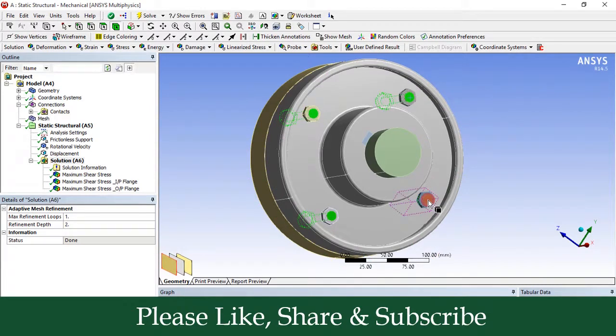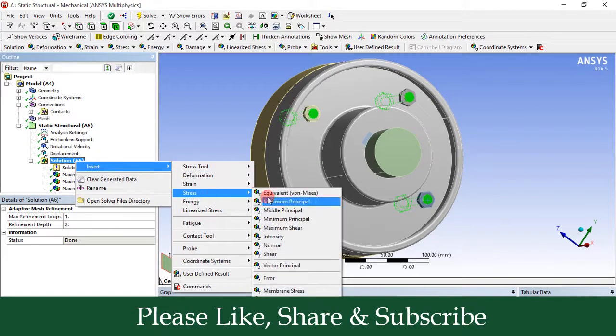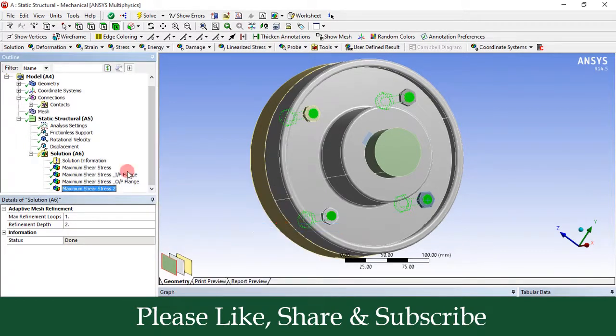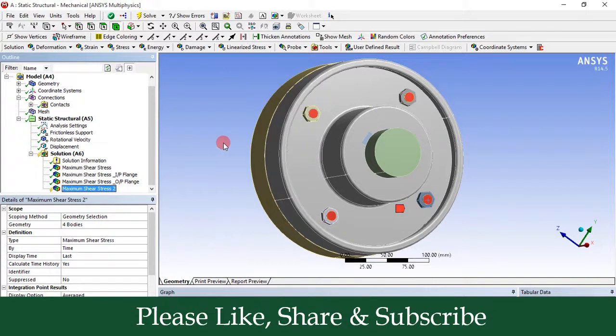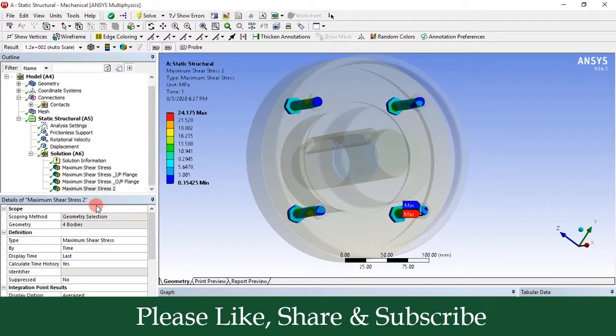So I have selected all these 4 bolts. Now left click on solution, right click on this solution, go to the insert, go to the stress and select this maximum shear stress parameter. So I have selected the 4 bolts for maximum shear stress parameter. Now right click on it and click on evaluate all results.